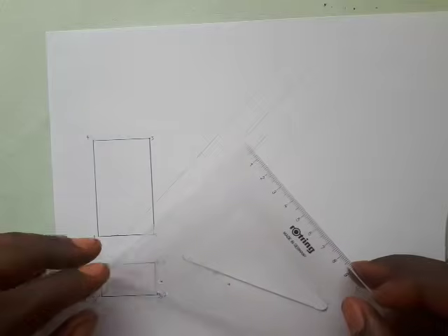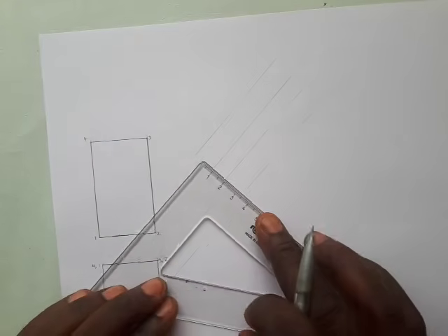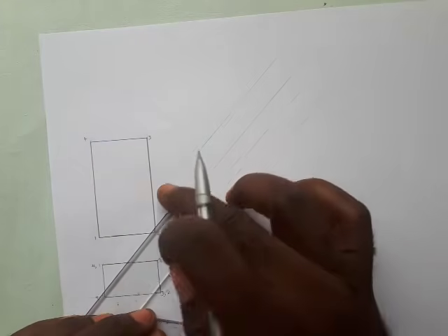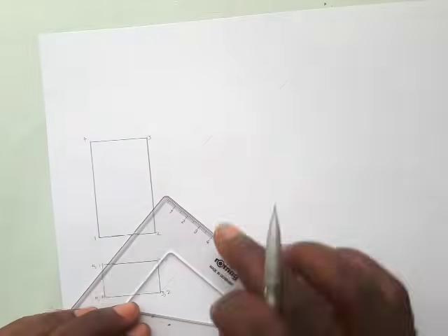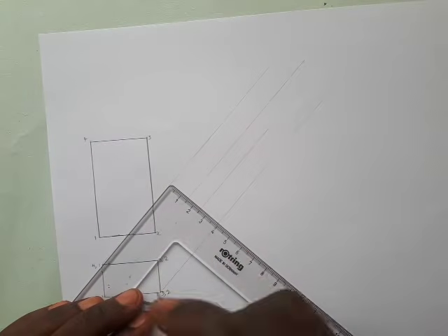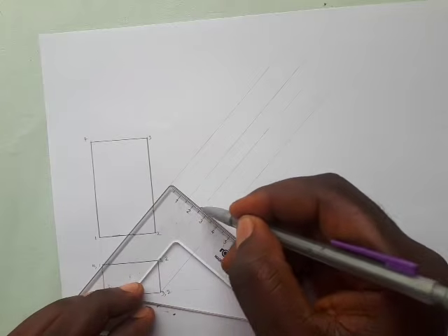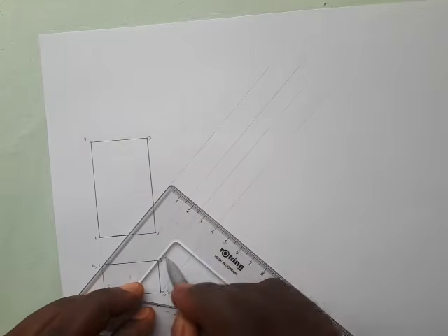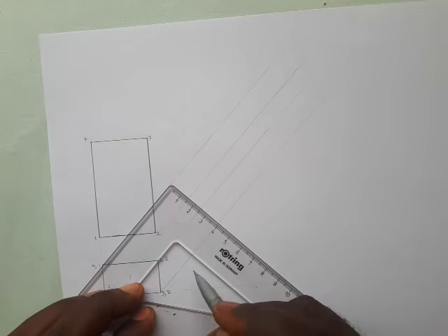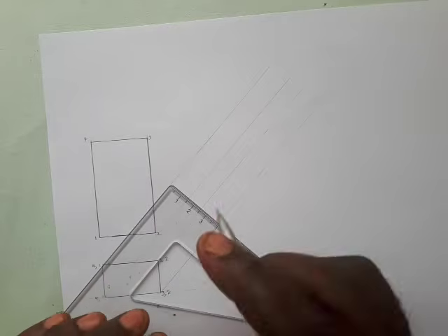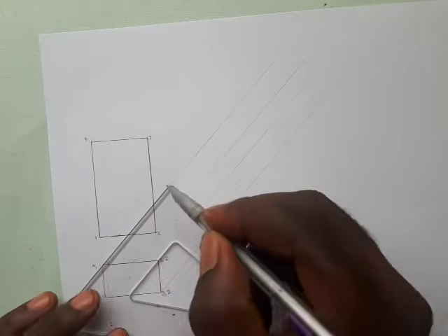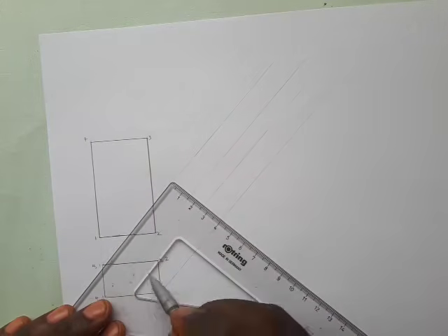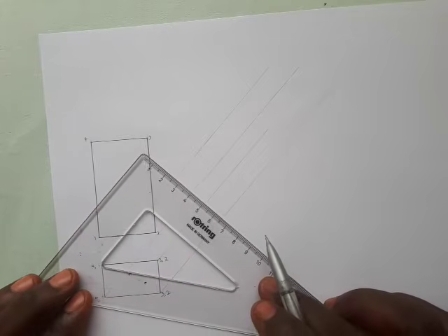So how? Just align your set square with any of the lines in this form at any point of your choice, wherever you want to start. So you align it like this, so you can see this is aligned. Now if I draw any line here, this line is perpendicular to all of these lines. But because the edge of my set square is broken, instead of using here as reference, I would like to use here. So I will move it in a little bit.